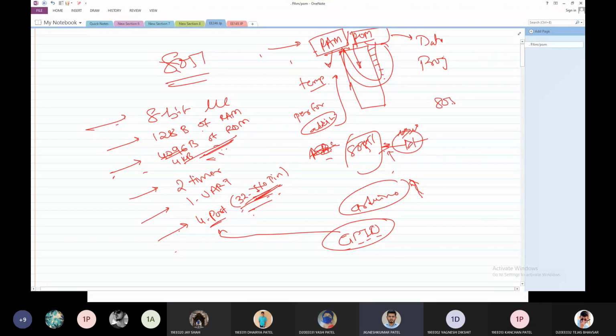But if I have 8085, what do I have to do? With 8085, you have to create a separate port. So what is a port? That would basically be a latch, 74LS373 or some latch. A bidirectional latch would be there, and using that you connect it with the address bus, and by using the address bus you create this as a port, and then I can connect my LED at this point. So to connect this LED, you require a lot of hardware in between. But if you have 8051, you can directly connect your LED on a single pin.